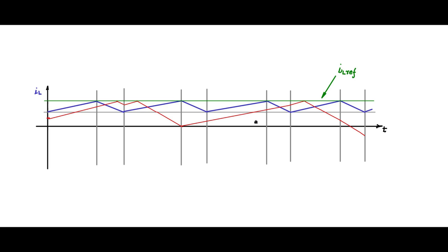So what I will do is try to extend this axis, and then draw a line which has the same slope as the falling slope of the inductor. Now the falling slope of the inductor here is minus V0 by L, or minus VB by L for the case of the buck converter. So we will use that same slope, continue it upwards.